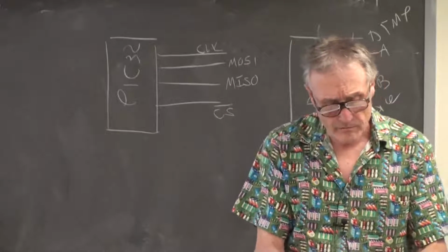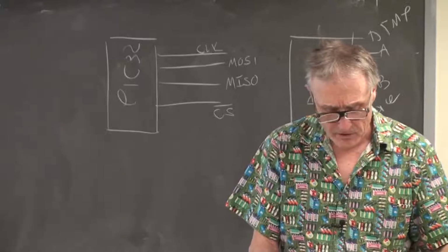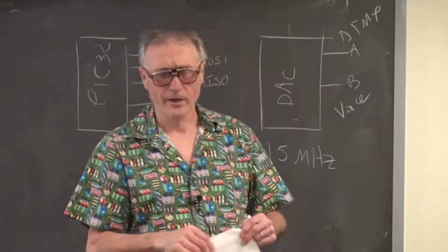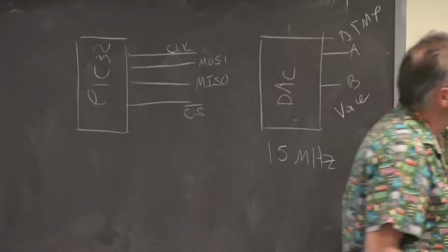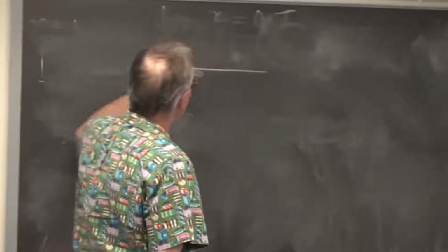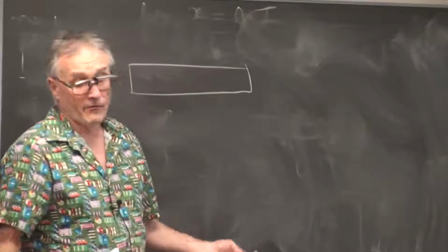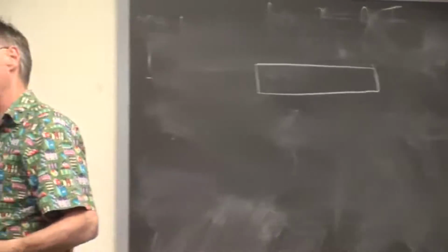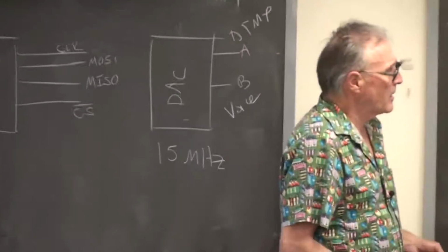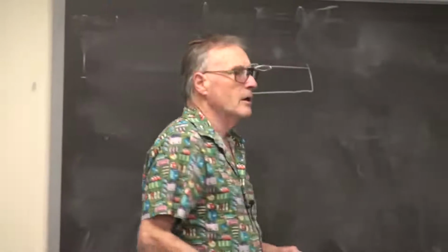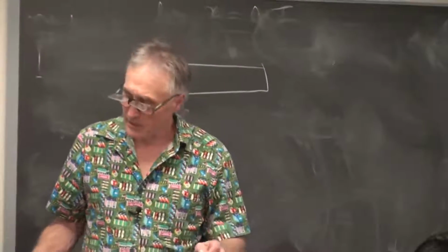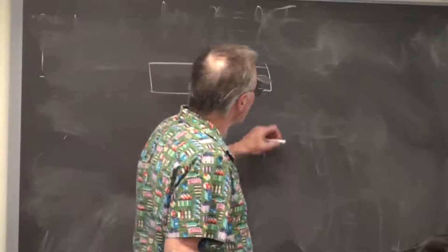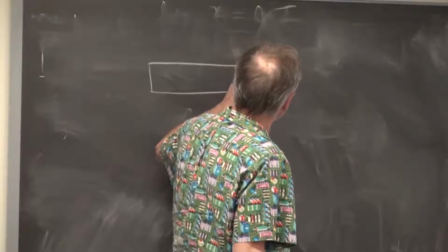So last time I talked about keypad, I sort of did a teaser on direct digital synthesis, probably just enough to be annoyingly confusing. But what we're going to do is take some variable register. I tend to say register because I originally implemented this in Verilog, but we're going to take a variable. It could be an int, a char, or a short, and I will tell you what difference that makes in a minute. And then we're going to increment this thing. We're going to feed it back to itself.